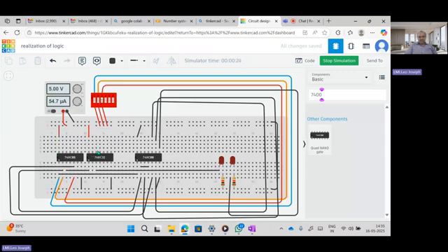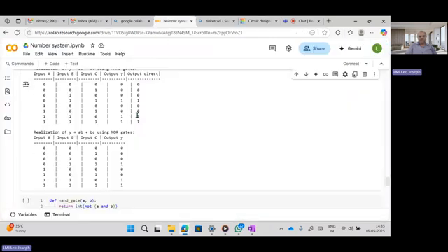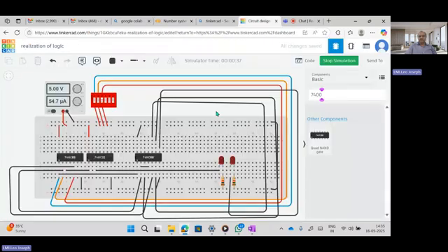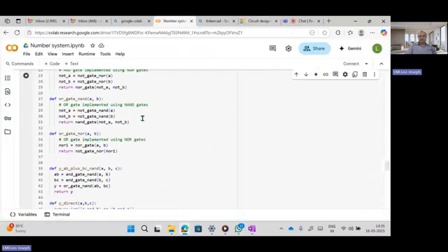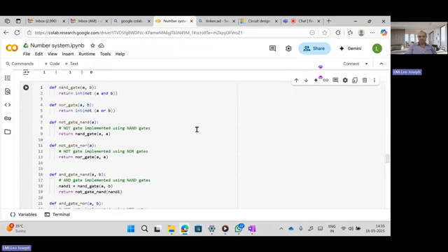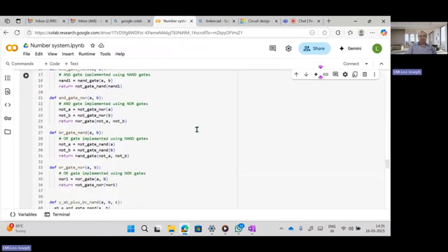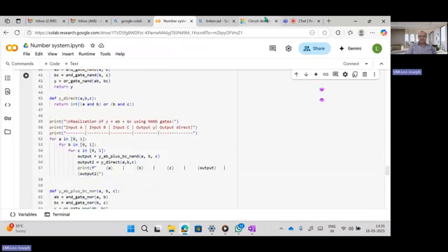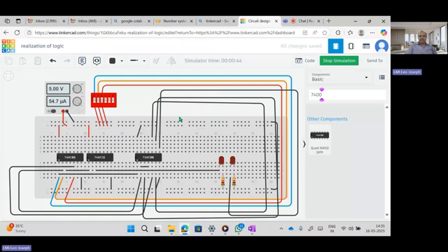So here, instead of using two ICs, I am using only one IC, but the output is the same. That is the power of realizing any circuit using a universal gate. This we have verified using both Python as well as Tinkercad. Tinkercad is the real circuit implementation practice, and Python is a coding practice. In this course, we teach you both coding and implementation skills, so that anyone can write code in Python, implement any circuit using Tinkercad, and verify both the truth table and the function of the IC in real time. This is how we can realize any circuit using online tools.